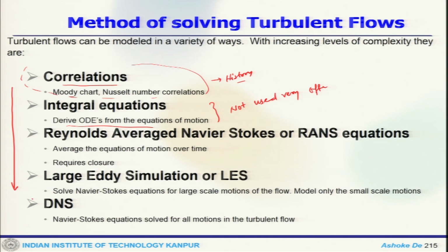And then LES is another choice beyond RANS, which will increase the complexity, but it also captures the turbulence in a better way compared to RANS. And finally, if you have enough resources in terms of computational power, then you can go for DNS for real life problems.